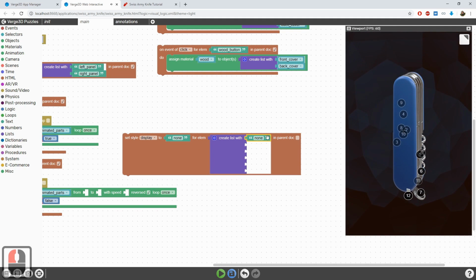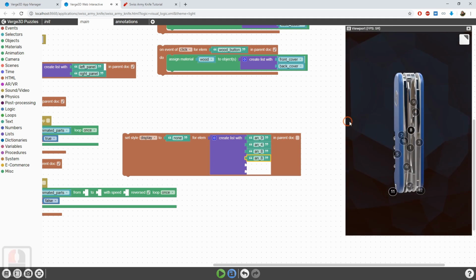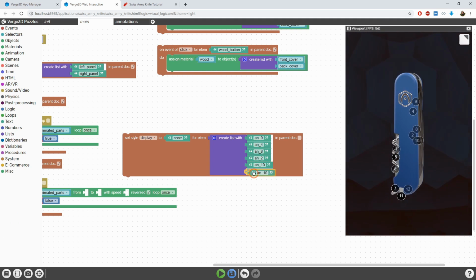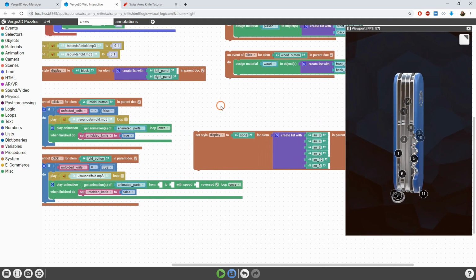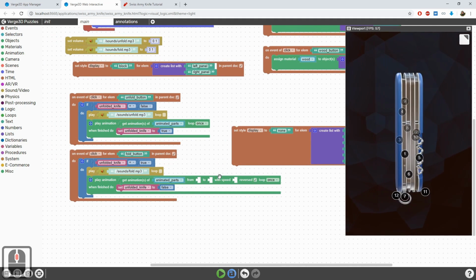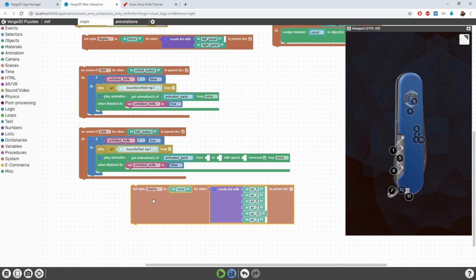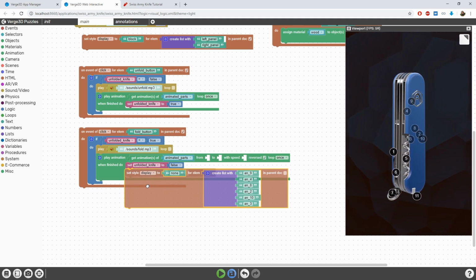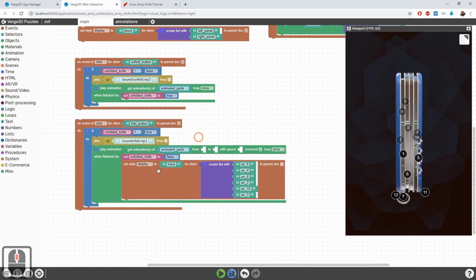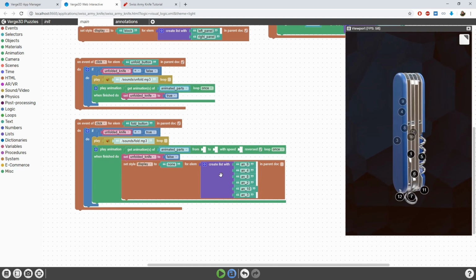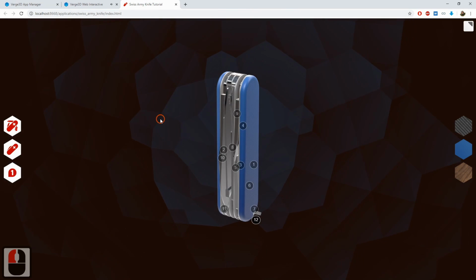Let's add the IDs for these annotations to the list. No need to enable in-parent-doc, since the annotations are added to the inner HTML file. This puzzle should be moved inside the when finished slot of the animation puzzle. So after the folding animation is finished, the listed annotations become hidden. Let's save and run the application.